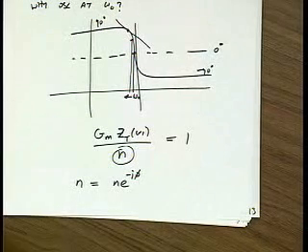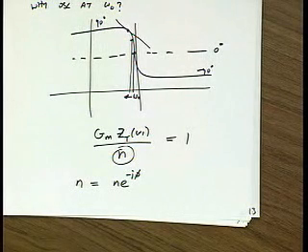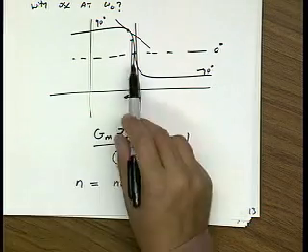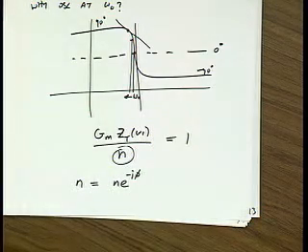Okay. Is the steepest point there also where you get the peak impedance from your resonant tank? So that's also another point, yeah. To maximize the oscillation amplitude and to minimize the power consumption, you'd also like to be at the peak. Okay? But if you have a clever circuit, bring it to class.